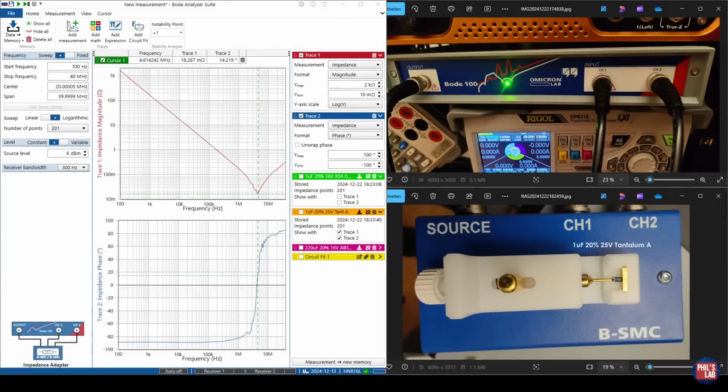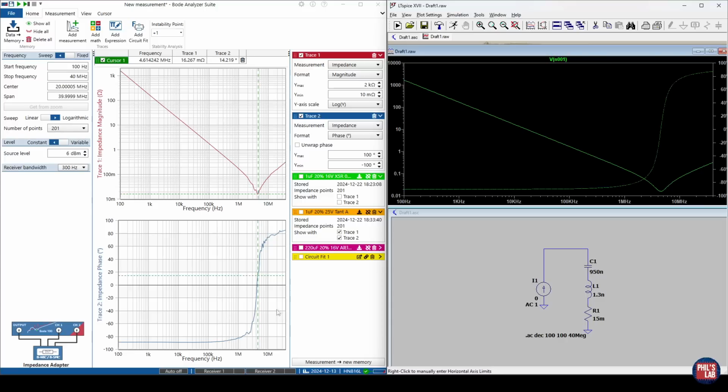In this video, we'll go through how to measure and characterize non-idealities of various capacitor types via an impedance measurement. From these impedance measurements, we can then extract parameters such as capacitance, equivalent series resistance, equivalent series inductance, and self-resonant frequency for modeling and simulation purposes. Throughout, we will compare between SMD multilayer ceramic capacitors, tantalum and aluminium electrolytic, and explore their similarities and differences. Finally, I'll show you how to import these measurements into LT-SPICE and compare the simulation to reality.